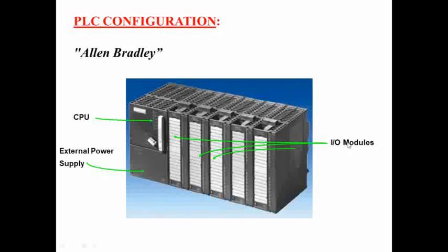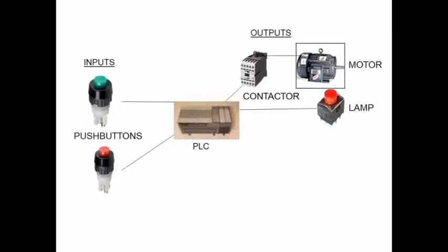Some input and output modules will be provided here one by one. There are some different structures as per their brands. Okay, so this Allen Bradley brand looks like this, and some internal features are also provided here. See this, these empty blocks will be provided for communication purposes, meaning that by using a port like RS232 or RS485, it will be connected here to monitor this system.